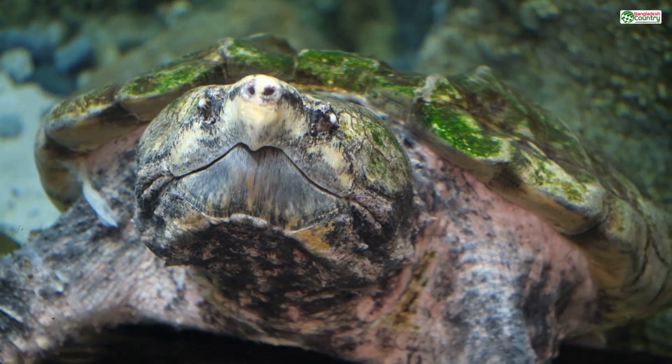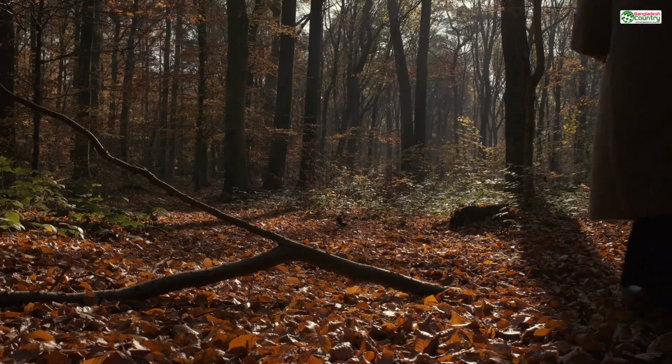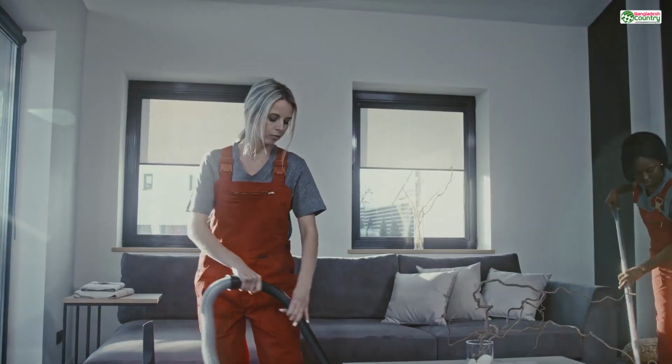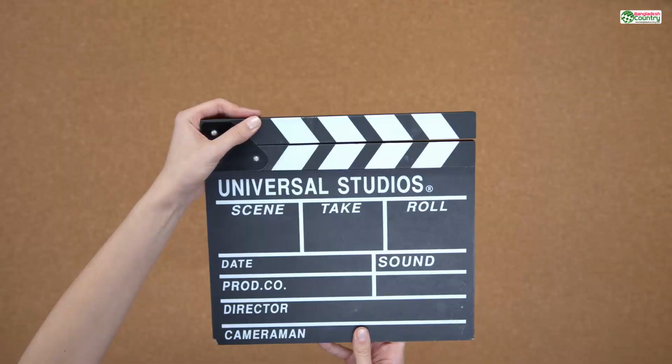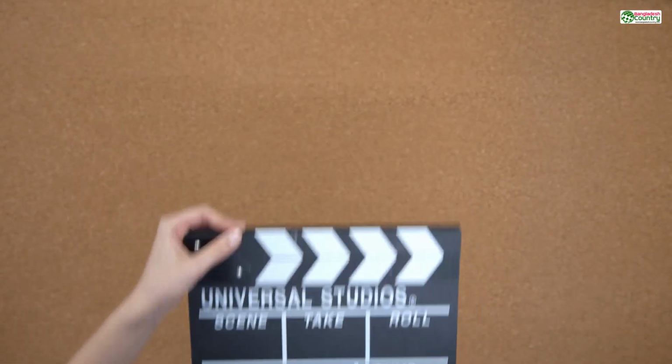And because they only touch your model at specific, tiny points, they leave behind much less scarring, resulting in a cleaner surface finish. So why wouldn't you use them every time? Well, generating these complex structures takes more computational power for the slicing software, and for very large, heavy overhangs, they might not provide the same level of rigid stability as their brute force counterparts.